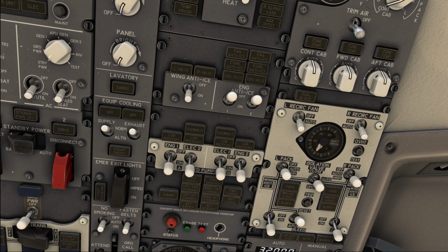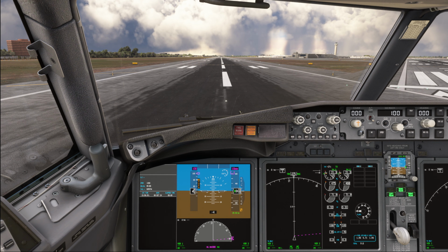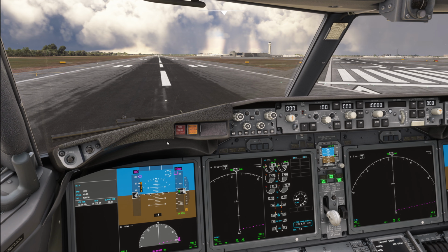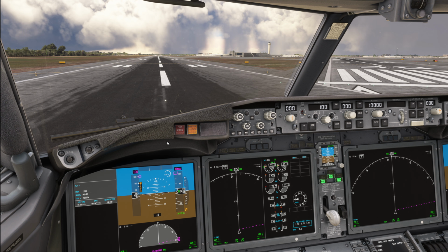So let's move on to the automatic flight and the flight control computers. So several enhancements have been made to the AFDS on the 737 MAX, and these include automatic disengagement of the autopilot following stick shaker activation, temporary removal of the flight director bars, an AFDS pitch mode transition following stick shaker activation, and the inhibit of autopilot nose-up trim when the airspeed is within the minimum maneuver speed amber bar. So let's make this one quick and short.